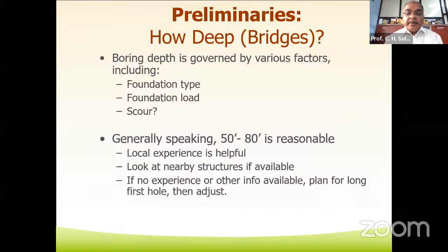How deep will you go for the bridges? What are the factors to be considered in deciding the depth of the exploration for the bridges? Here it has been mentioned that boring depth is governed by various factors, including first, foundation type, second, foundation load, third, scouring, etc. Generally speaking, 50 feet to 80 feet is reasonable, but local